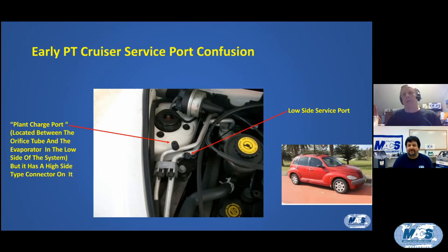And what I typically do when I'm talking to them is, all right, what I'd like for you to do here is let's take this vehicle and get it close to a water hose somewhere. Have somebody help you. Let's start it up. As soon as you start it up, I want somebody misting some water on this condenser, and let's see what it does. Pressures drop on down. It's blowing nice cold air. So cut it off. I said, we found your problem.